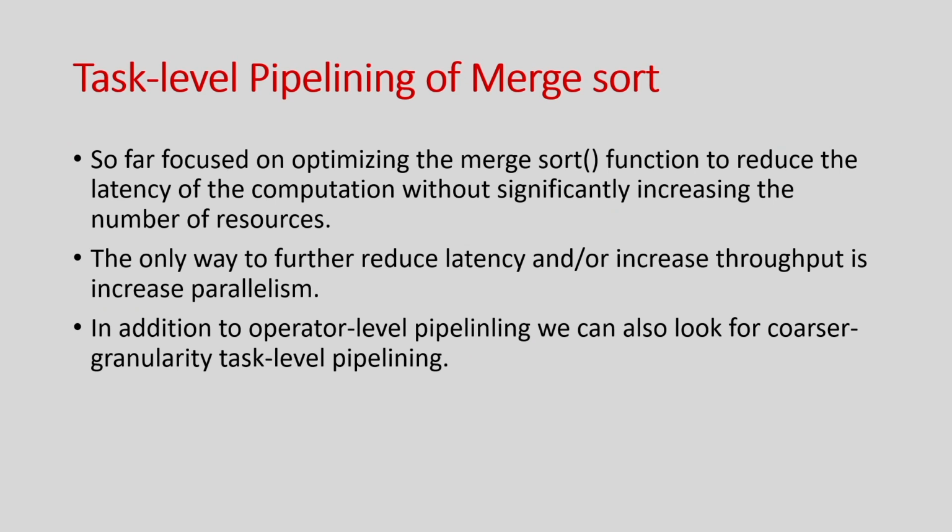The next is the task level pipelining. So, we have already a sequential version of the code, and we make the code most efficient one, right. There is no further efficiency improvement possible. So, the next thing is to parallelize the execution, right. So, that is what the task level pipelining is, and it is one of the most powerful optimizations of high level synthesis. So, the idea here is, can I parallelize the execution of the loop, right. So, you can understand here